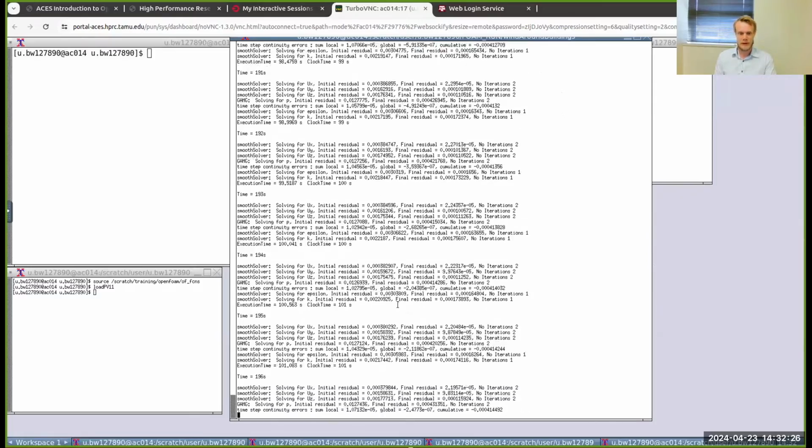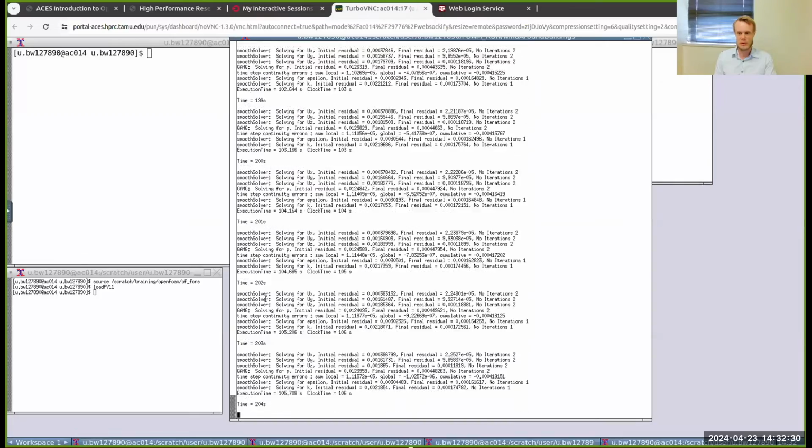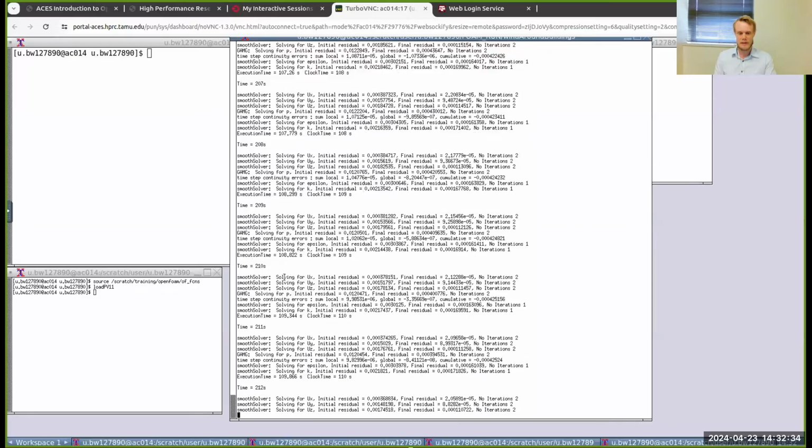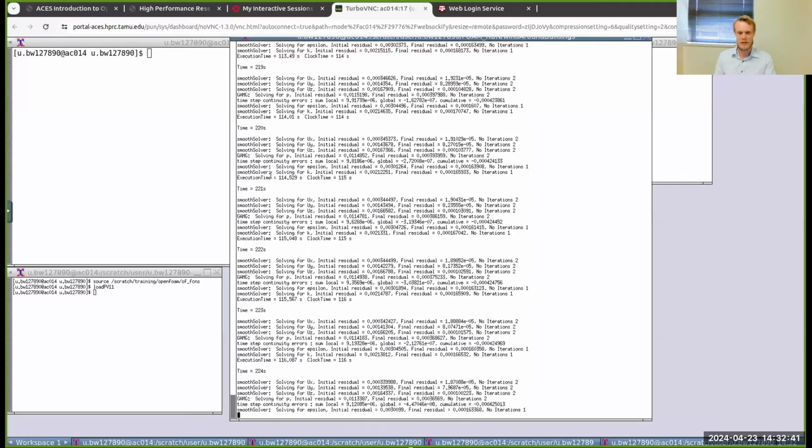Okay. As we come up on 200 seconds here, you saw that it made a little pause. That means it was writing. I didn't say before, but in the controlDict, I told it to write to file every 100 seconds or every 100 iterations. So that's why it made a little pause there.